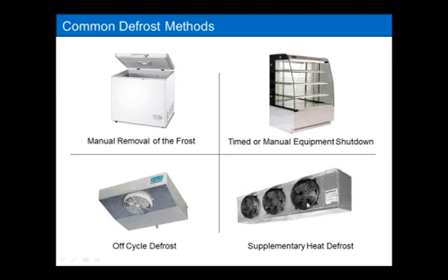And then when you get into your low temperature world, your freezers, your walk-in freezers, reach-in freezers, it's going to use some type of supplemental defrost. Supplemental heat, some type of extra heat, is going to be added to the coil on a regular basis and defrost the coil in that method. So tonight we're going to talk about these two popular methods. We're going to talk about the off-cycle defrost technology, and then we're going to concentrate on the electric defrost system used for the supplemental methods. The electric defrost is pretty popular when it comes to your standard low temperature walk-in freezer, reach-in freezer. So we're going to concentrate on these two types of defrost systems.